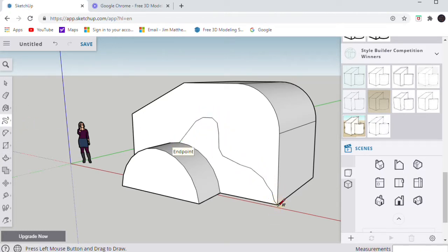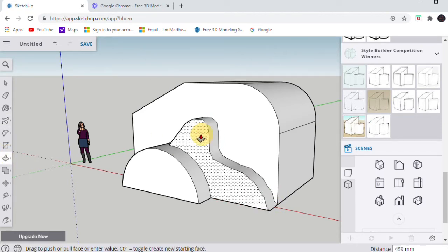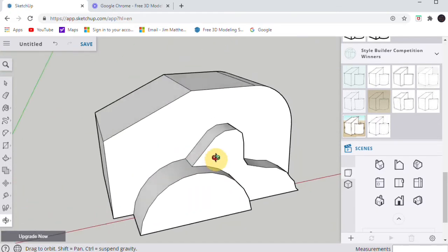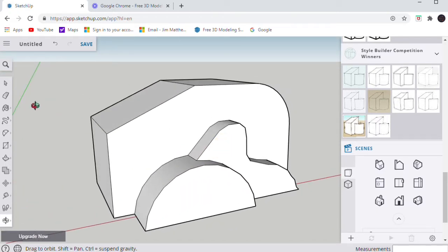I've now moved on to the pencil, held down to the freehand pencil sketching tool that allows me to draw a curved line. We're just doing rough prototype modelling on here at the moment, so that's quite a useful tool to use for that. If we need to be more accurate, then we'd probably produce that using a series of curves instead of a freehand line.